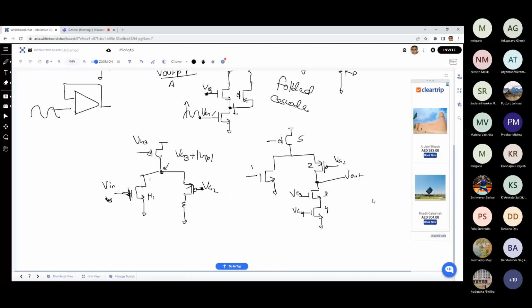And how it is saying, well, ultimately this is acting like a current source. This one has been biased with a constant voltage source. And if I assume that this is acting like a good current source, once again in the small signal analysis, I will for the time being ignore it. Of course, in exact analysis, you don't ignore. In exact analysis, I have to take into account the RO5. So that part for the time being, you keep in mind. But if I assume that this is an ideal current source, I can ignore.